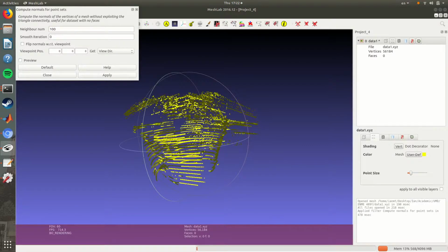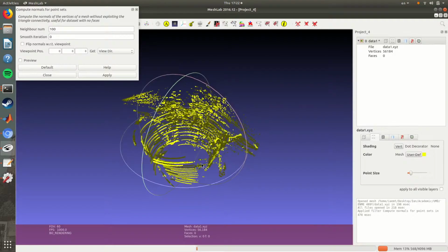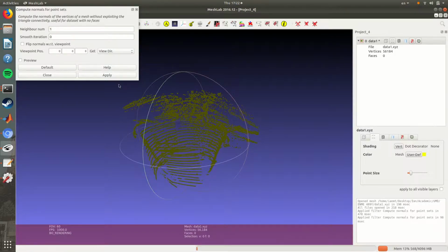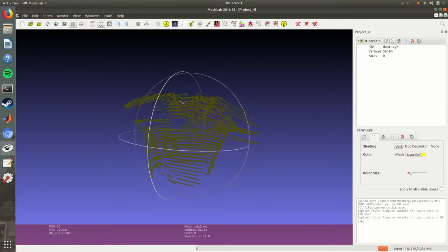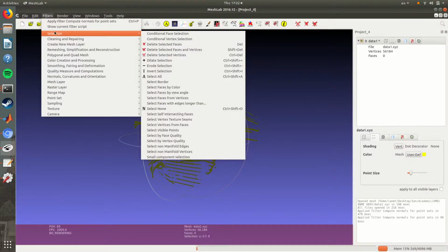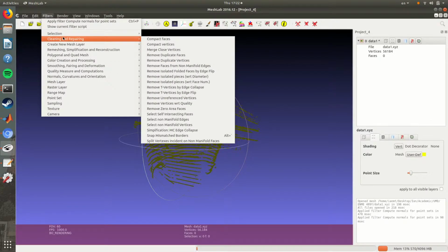So we're going to use the Poisson, just using the typical values. And so here is the mesh that is resultant. It's a silly bulbous looking thing with that manifold kind of in the middle. The way to get rid of those extra surfaces is to use the rectangular face select tool.